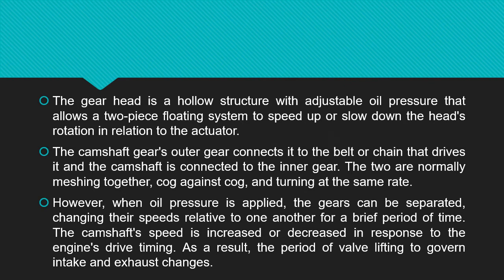However, when oil pressure is applied, the gears can be separated, changing their speed relative to one another for a brief period of time. The camshaft speed is increased or decreased in response to the engine drive timing. As a result, the period of valve lifting to govern intake and exhaust changes.